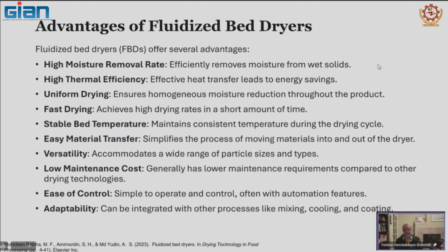It's all possible within, of course, a prescribed range of particle classification. Low maintenance cost. We touched on this earlier: because there are no moving parts within the bed, the only rotary piece is the blower that is providing you with the fluidization air.